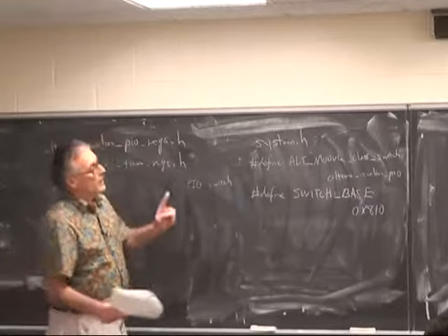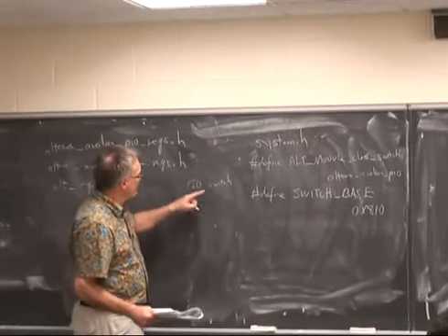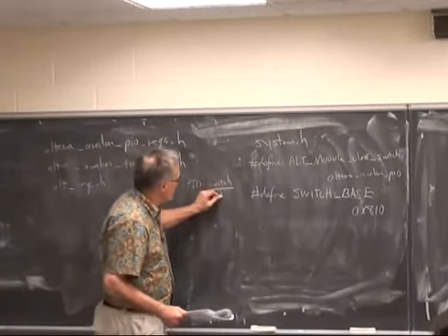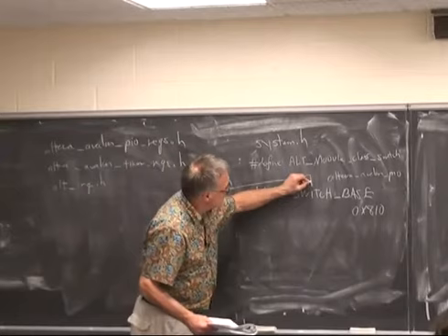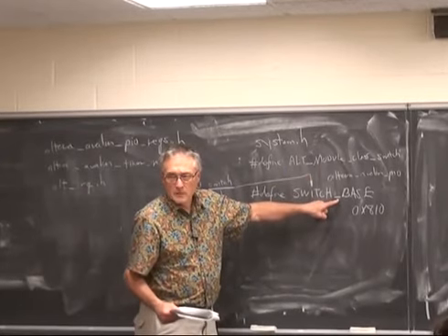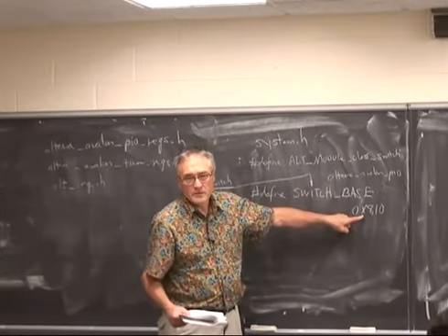So, what SOPC Builder did, for reasons only it understands, is to take this lowercase version, uppercase it, and append underscore base. And then assign an I/O address to it.